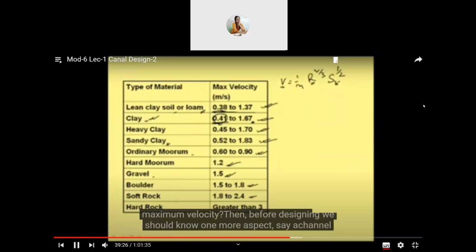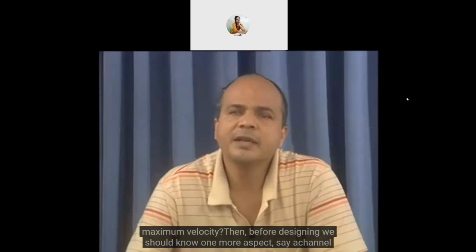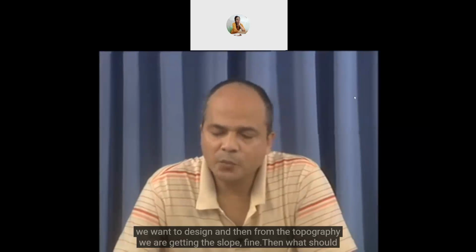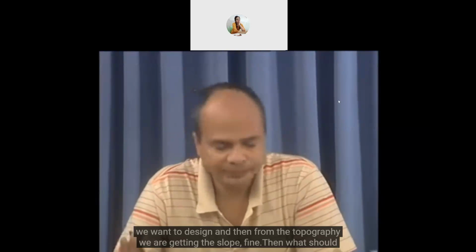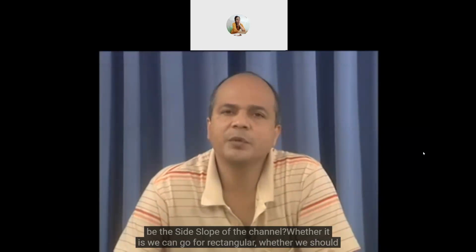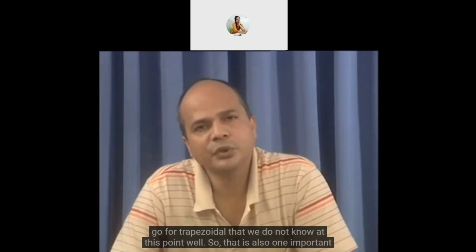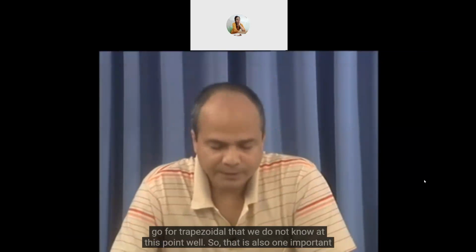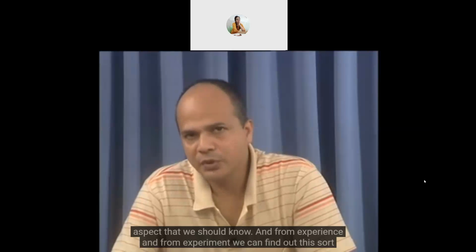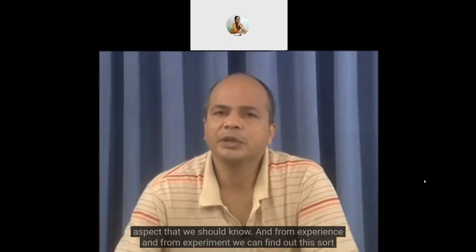Then before designing, we should know one more aspect. Say a channel we want to design, then from the topography we are getting the slope, fine. Then what should be the side slope of the channel? Whether we can go for rectangular, whether we should go for trapezoidal, that we are not knowing at this point. So that is also one important aspect that we should know, and from experience and from experiment we can find out this sort of value.